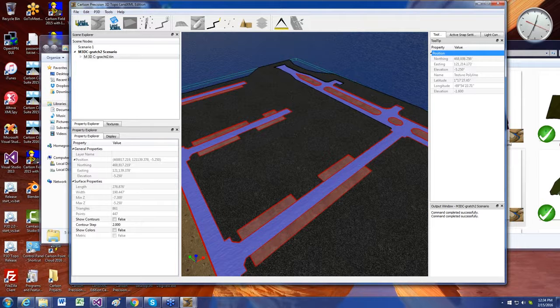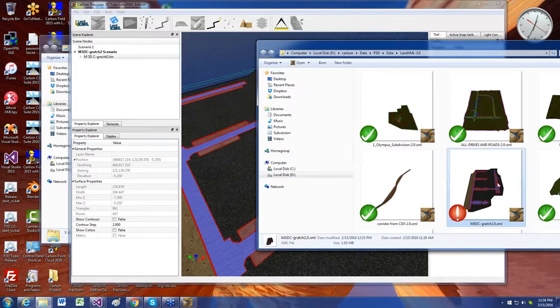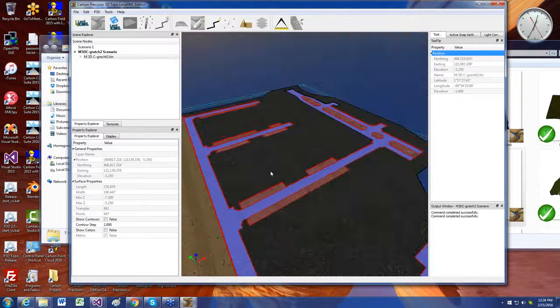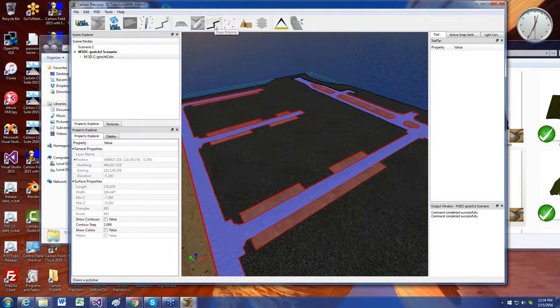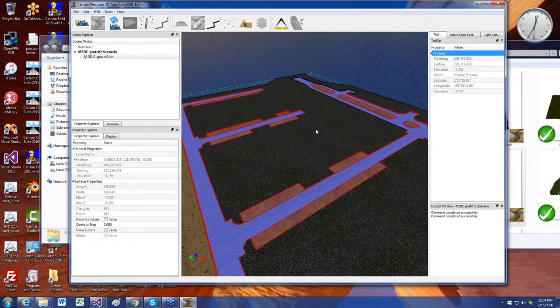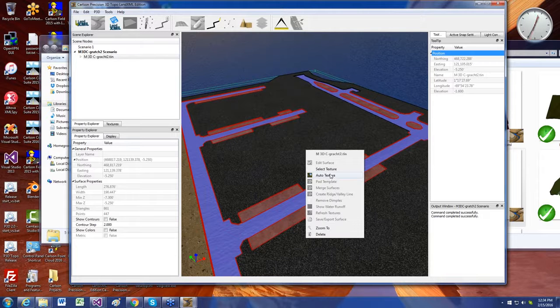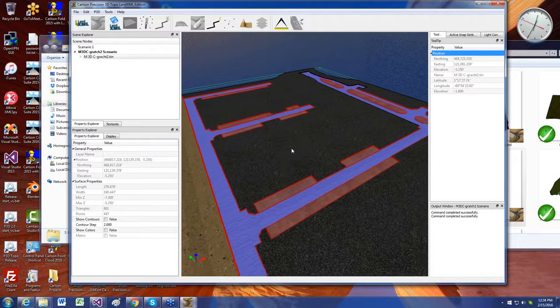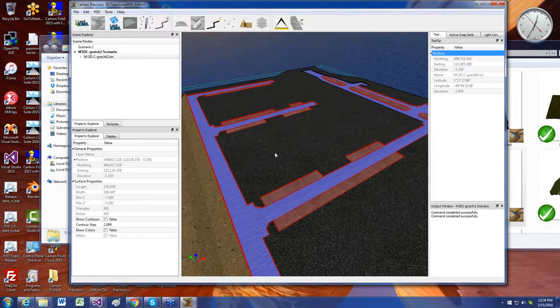That's exactly right. And with the free viewer, you also get the thumbnail control as well. This is actually P3D running in the LandXML free edition, and you can see that you have the draw polyline, that there's a number of commands. The most important one, though, is select texture and auto texture. So the really important thing about the free LandXML viewer is not only do you get this pretty LandXML picture, but you can also texturize it, and you can basically upgrade it, and you can set colors on all of your polylines and alignments and parcels and so forth, and you can re-export that back out.